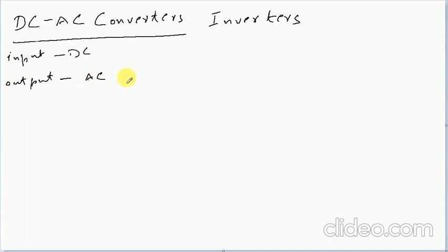of AC type. Within the AC, there are a few possibilities: either we can have sinusoidal output, in the form of alternating current or voltage, or we can have a square wave as an output. But for most applications, we require that the voltage provided to them should be of sinusoidal type. So these are the inverter circuits which are of most interest to us and everyone else, and that is why they are quite often discussed and investigated.